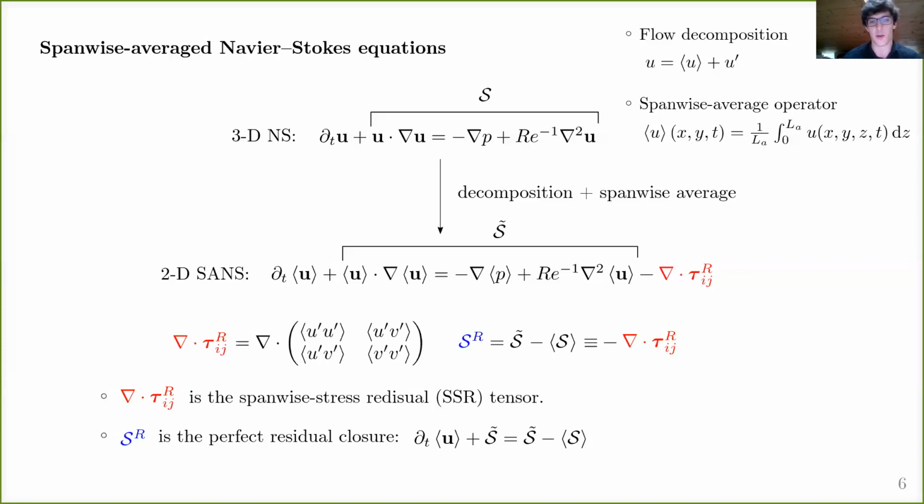So in this work, we will focus on the closure of this in blue that we see here. That is a direct source term for the momentum equation. Again, adding this source term to the momentum equation changes the flow dynamics from a classical 2D to this spanwise average picture that we were aiming for.